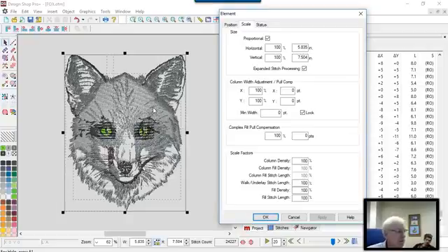This is where this changes actually quite drastically from dealing with a wireframe design. Scale factors exist in wireframe designs as well, but with things like density, it is going to be multiplying that scale factor by the density number, which is the space between the stitches. So the larger number, the farther apart the stitches get. With expanded, it is doing that off of the stitch count. So I need 150% times the number of stitches. So the bigger the number, the more stitches you have, the closer they are. So it works very differently between expanded and wireframe.